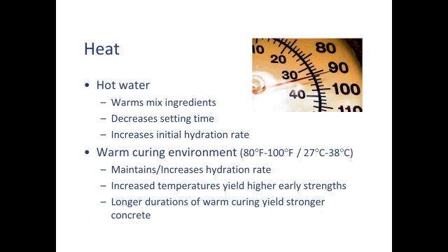Now, it's winter here in the northern hemisphere, and your shop is probably cold, your mixed ingredients are cold, and cold concrete doesn't react very fast. I'm going to mention that when I talk about retarders next. Well, to kind of kickstart things, use hot water as your mix water. That's going to warm up all your ingredients from maybe being 50 degrees Fahrenheit or 10 degrees C up to around 20 degrees C, that 68, 70 degrees Fahrenheit. It's going to help get things going so that it can generate enough heat in a meaningful amount of time.